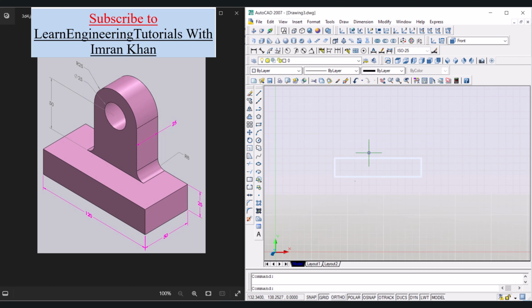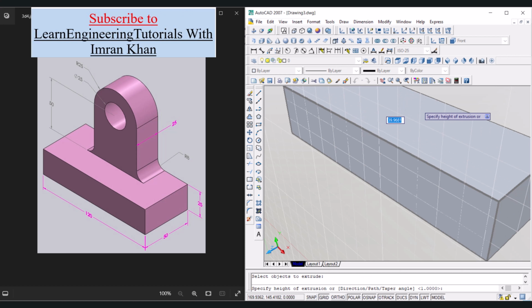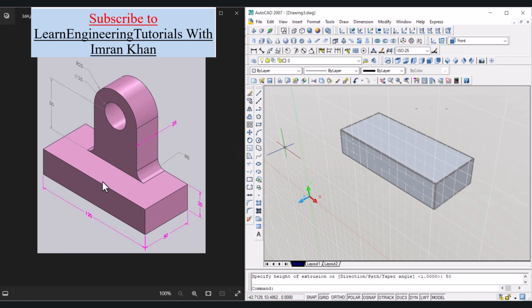Now we have to give some thickness. So for that go to isometric view, click on extrude, click on this rectangle, press enter, and now we can give the thickness of 50, enter. So the lower base of the object is complete.